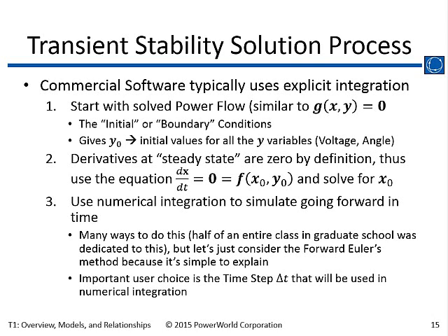This is something that in an undergrad power system analysis class you use to get the internal angle on your generator. We do that. We back solve through all the models, through the machine models, the exciters, the stabilizers, the governors, and set all the initial values of the state variables so they're all set equal to steady state. When you start a transient stability run and you don't put a disturbance on it, it should run flat. Nothing should change.